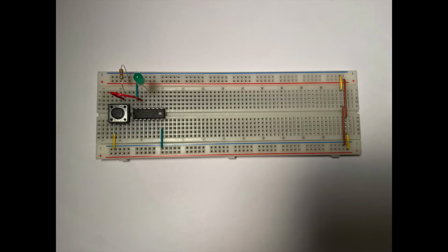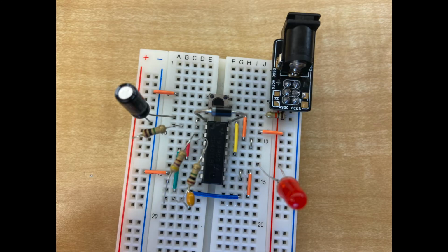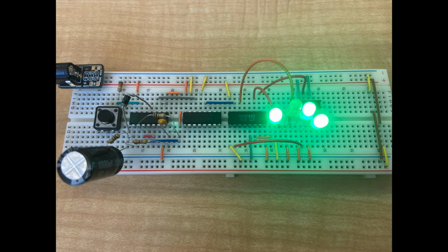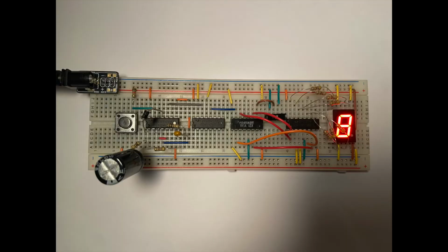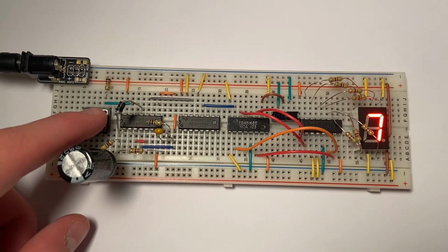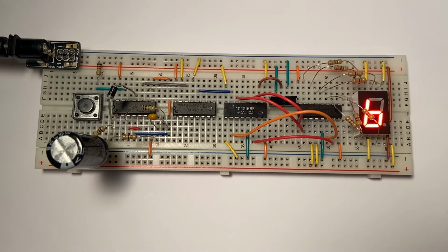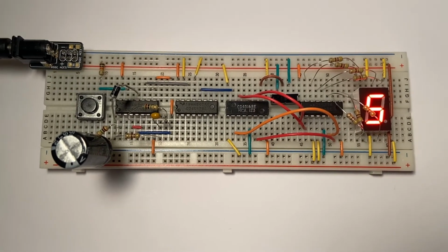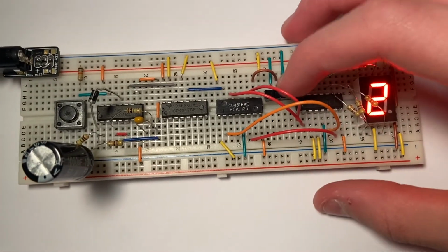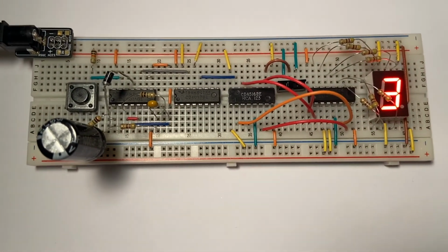The main things that we use to make up the counting circuit are the button input, the NAND gate oscillator, the decade counter, the decimal counting binary up-down counter, the binary counting decimal decoder, or the 4511 chip, and a 7-segment display. When all combined, the counting circuit is capable of counting in both directions, up and down, in numerical order. However, it can only count to 10, and that's why we are able to use a 7-segment display which only displays digits 0 through 9.